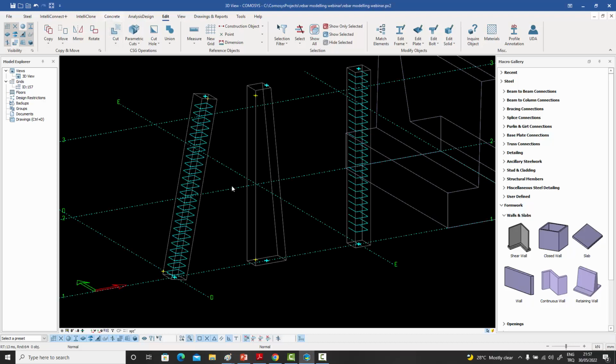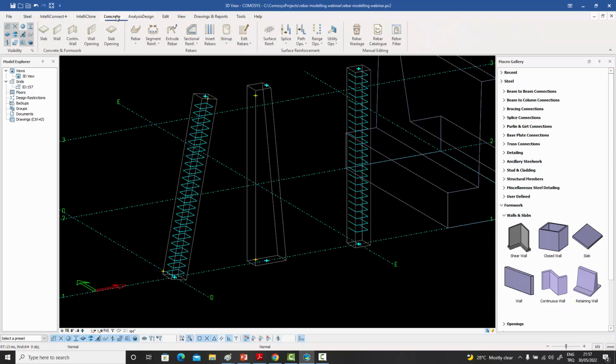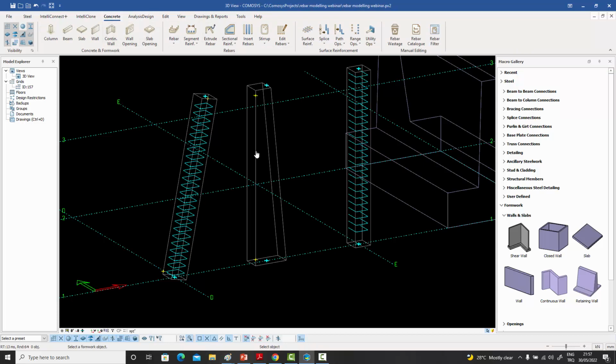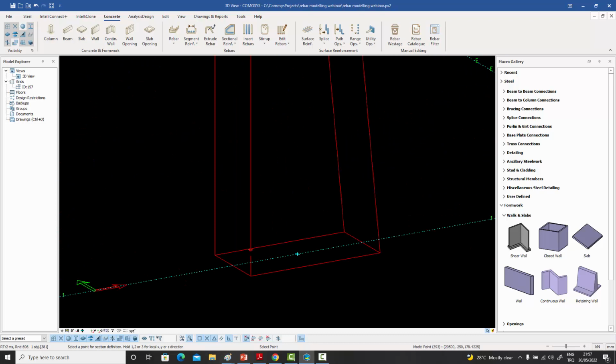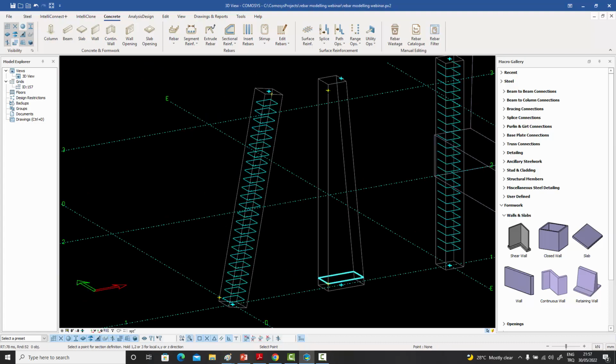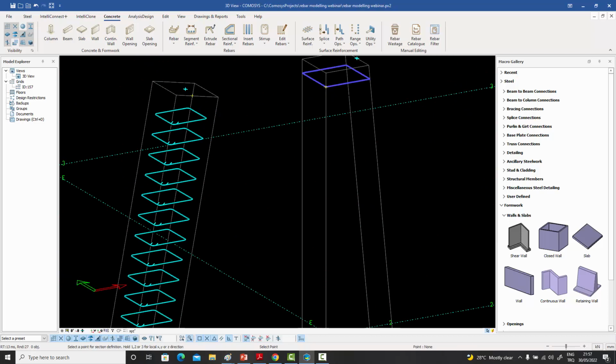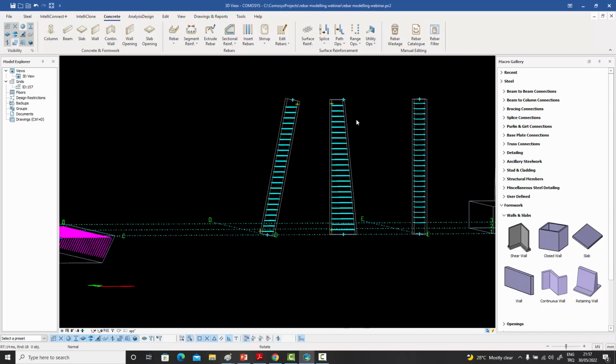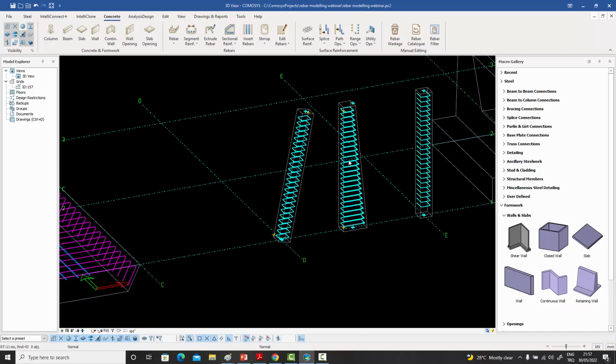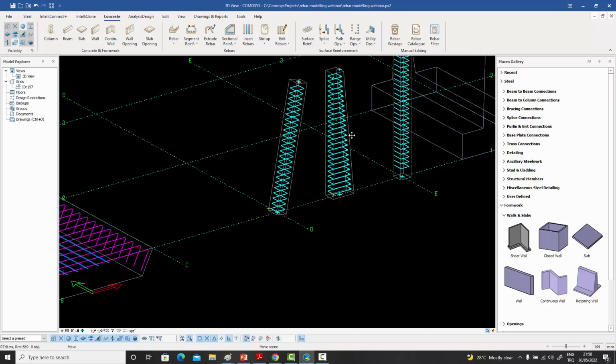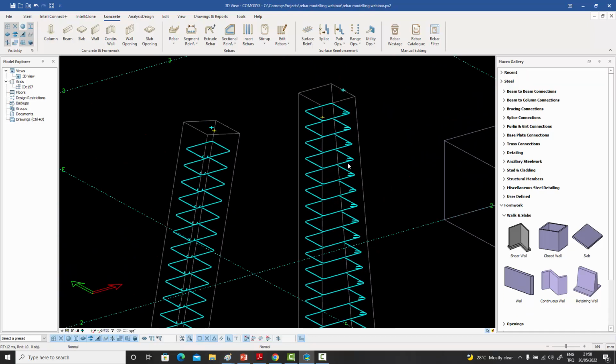Now, in the examples I've shown so far, I have taken a section at 2 points and the bars have gone from point 1 to point 2, but the shape of the bar has remained constant, whatever the direction may be. But what if we had a tapered column like this? In that case, what would happen? So if I go to my sectional command once again, select my tapered column, select the first point by pressing 3 because I want them in the global direction, right click to accept all, and let's say put the hook at this point, and then I go up and select this point, press 3 and right click again. Now as you can see, because the column has been tapered and the sections were different at this point and at this point, it has done a linear interpolation from that point to that point. And I've created stirrups which vary in a tapered way.